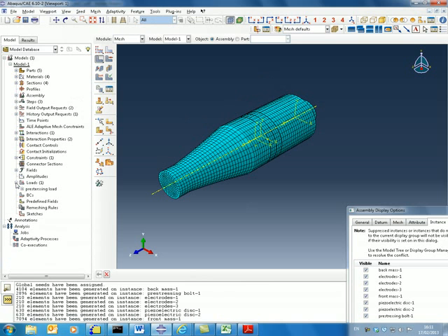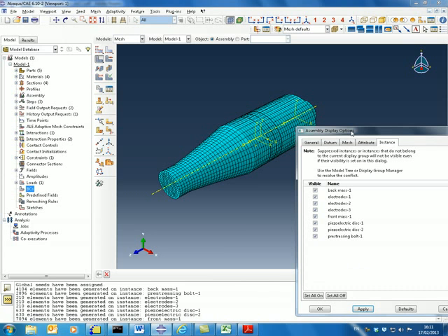Finally, we need to assign a boundary condition for the piezoelectric material, and at this stage piezoelectric materials can be assigned different types based on what frequency you require to resonate. If you are required to resonate at resonance frequency, then you have to define the electrical boundary condition on both sides of the piezoelectric material.